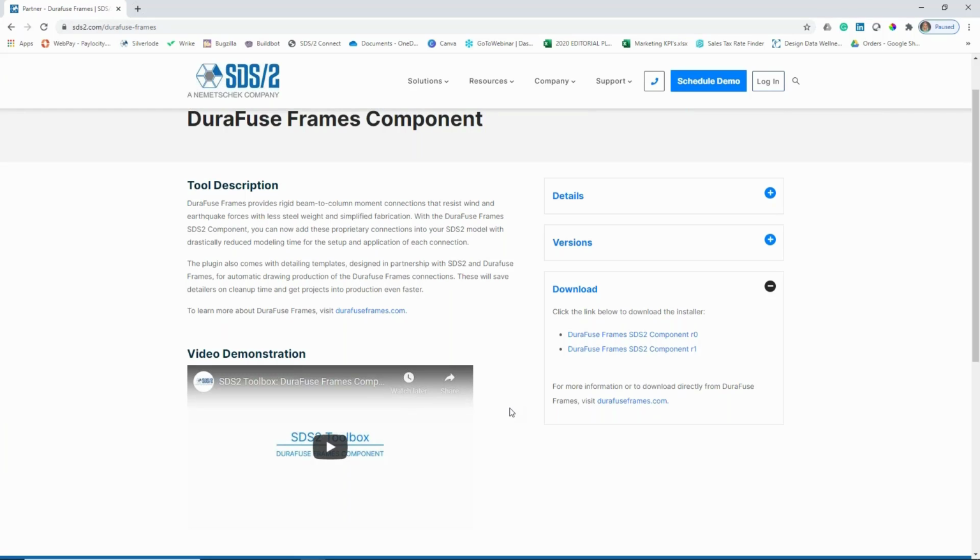Can we have any welded connections in lieu of bolted plates? Yeah, that's a great question. So the reason the fuse plates are bolted is so they can be taken off and replaced after an earthquake. We don't have details where the fuse plate's welded on, but we do have details where the top plate is welded on. We can discuss that with the engineers.